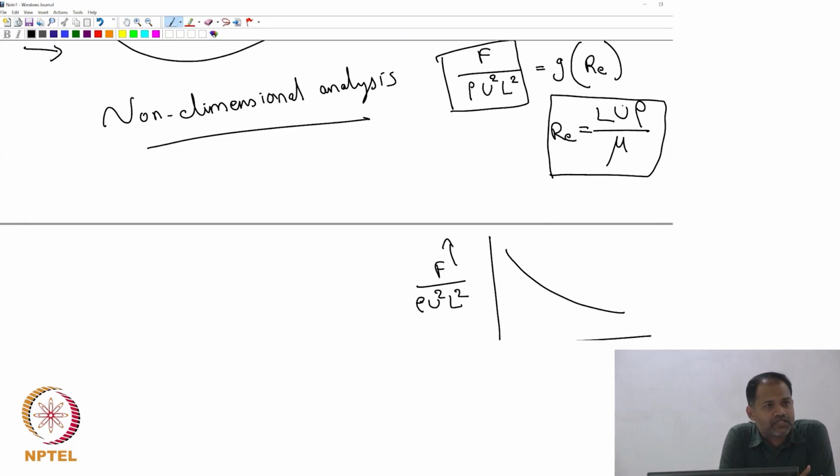Okay, the non-dimensional analysis is not going to tell you whether this particular form is Reynolds square, or is it exponential of Reynolds, or is it sinusoidal of Reynolds. We won't get it. We will not know exactly what it looks like, but we will know what are the numbers that are going to be connected by a particular form of function. Okay, and that's all we care about, because that is enough in most of these cases, because things basically get into a compact form. Doubts?